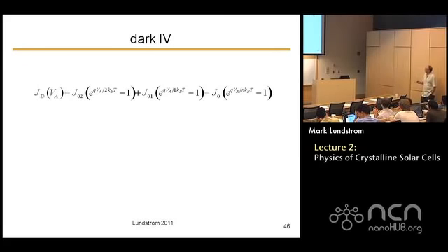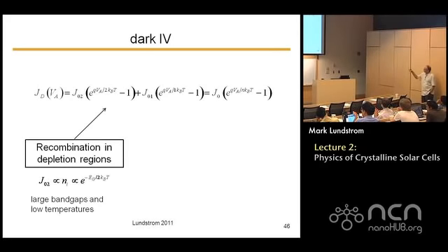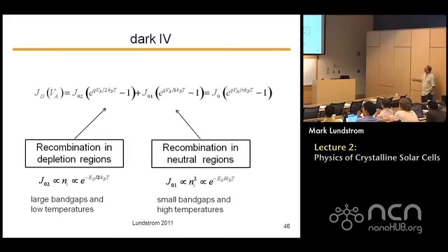Okay, so you really have to separate them out. The important point was the N equals 2 component is proportional to Ni, so it goes as e to the minus Eg over 2kT. The N equals 1 component is proportional to Ni squared, so it goes as e to the minus Eg over kT.